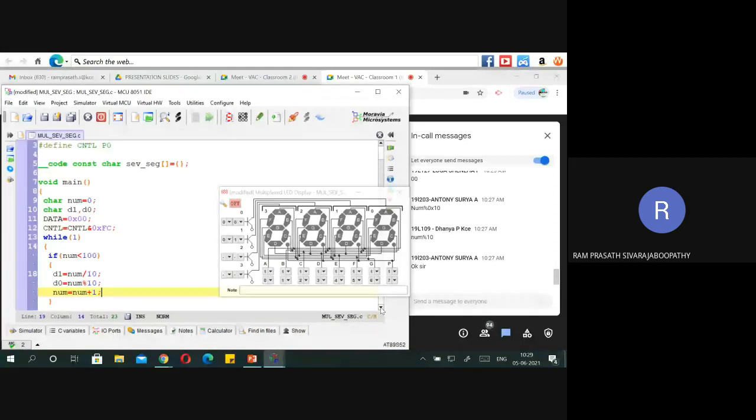For displaying just 2 digits, there is no need to go for a looping concept, as it might go in a tedious way. Here I am simply going to enable or disable that pin. First you have to keep the data, then you have to control the digit.